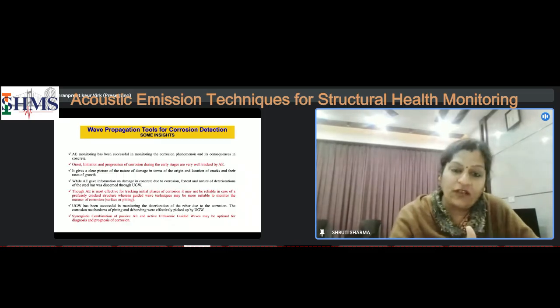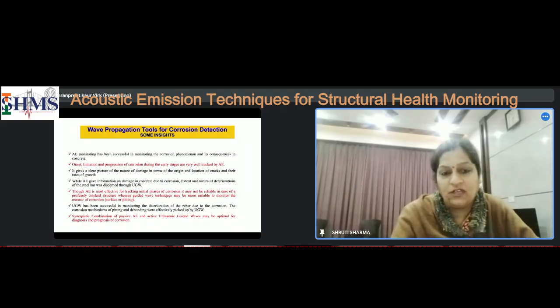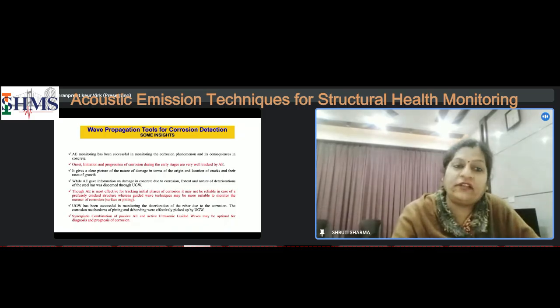Maybe we can use AE for measuring initiation, and progression can be picked up by various tools. One of them may be ultrasonic or other things. So the combination is the key. Yes, so just one example that corrosion detection is very well tracked by acoustic emission. Next slide.